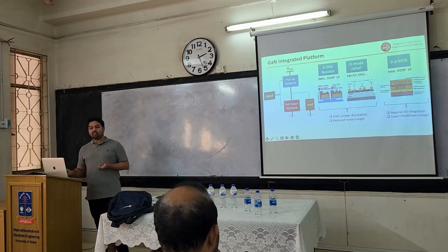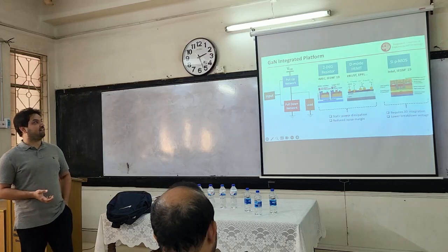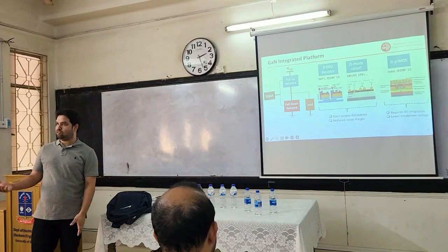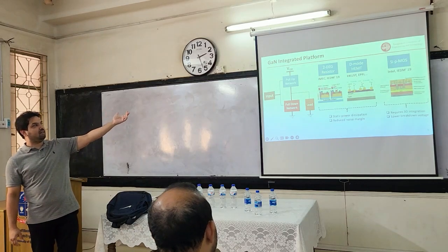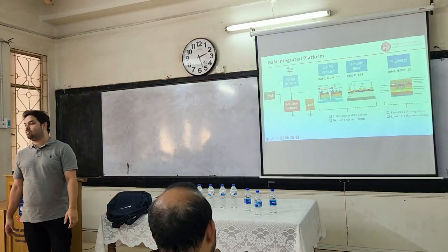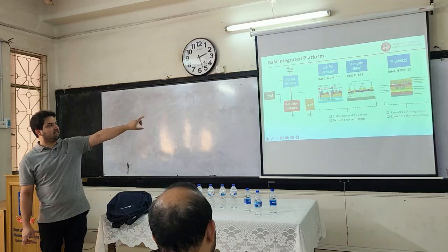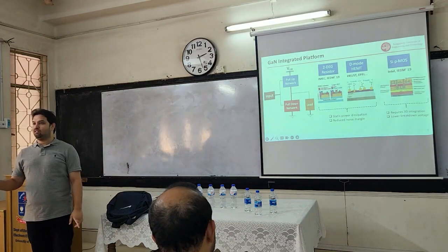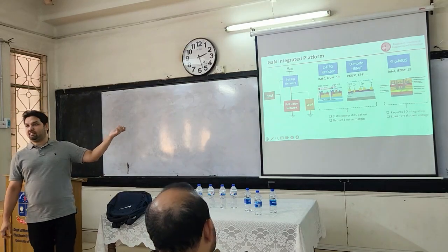It's not like there is no platform right now. There are a few platforms available. For the pull-down network, they only use N-type GaN transistors, which is what everyone should use. But for the pull-up network, they use different technology, basically either an N-type transistor or a resistor. For the pull-up network, either you use a depletion-mode transistor that is always on, and when the transistor is always on, it's basically a resistor, or you use a real resistor.